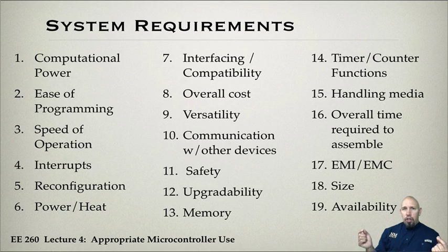Okay, so if, for example, you want to use your microcontroller system to do some analog processing, let's say your guitar signal. You got a guitar, and you want to be able to do some signal processing with your guitar, and so when you do analog to digital conversion in order to put the analog guitar signal into your computer, it takes a little time to do that conversion. Then it's going to take some time to do the processing, okay, which may involve some number crunching, may involve some other things, logic functions or whatever. And then it's going to take whatever signal it needs to and output that through some means. And so the whole process from the time it starts, from the time it grabs a value to the time it puts out a value, there may be some delay, and that's often referred to as latency.